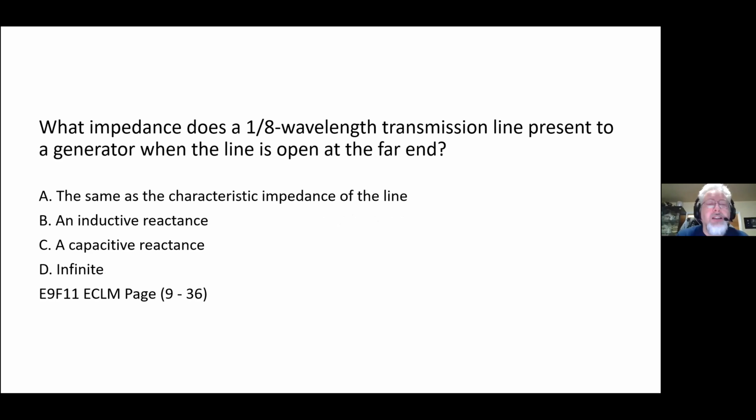What impedance does a 1/8 wavelength transmission line present to a generator when the line is open at the far end? A, the same as the characteristic impedance of the line. B, an inductive reactance, C, a capacitive reactance, or D, infinite? Charlie is correct, a capacitive reactance.